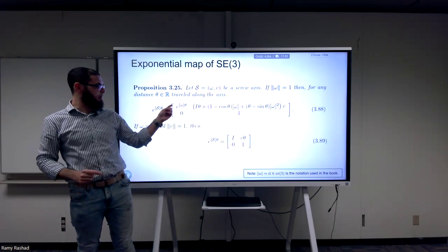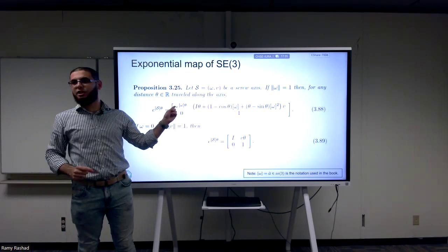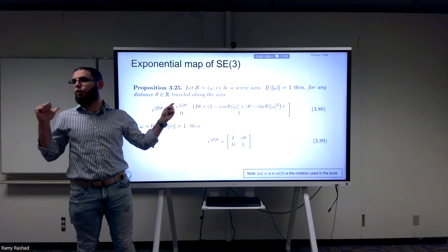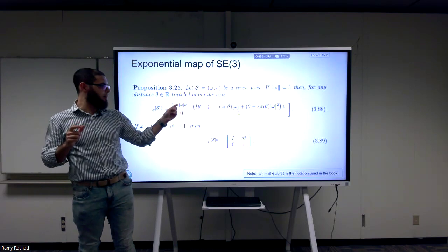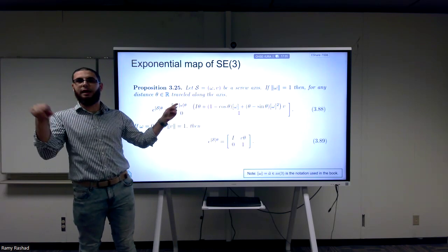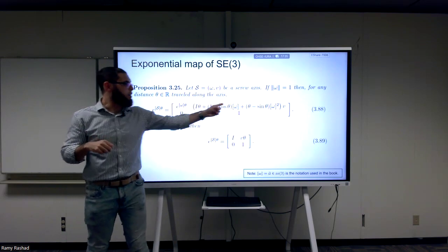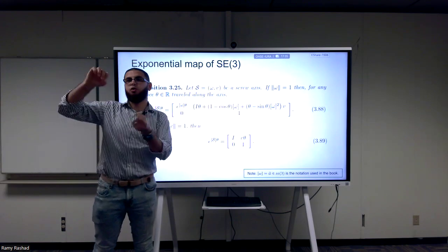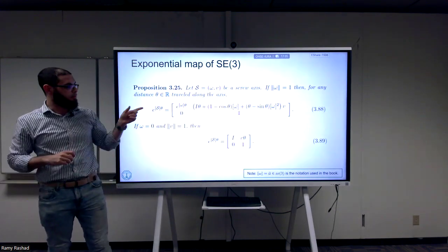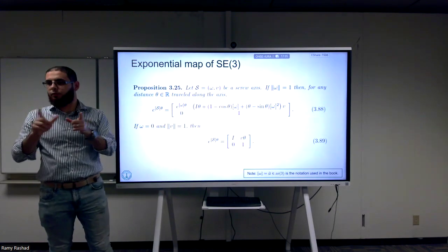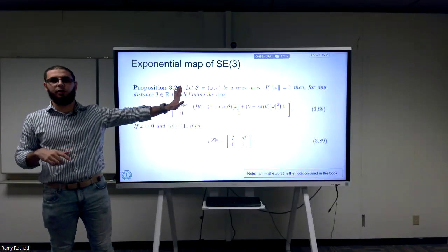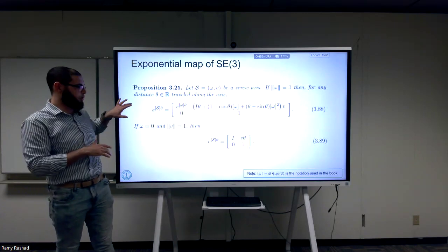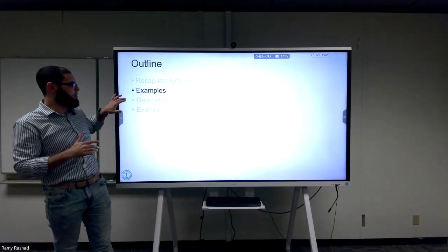This expression is the same. So we have here a rotation matrix. How do we calculate this part? By the Rodriguez formula, because the Rodriguez formula would take an angular velocity, and you can calculate with it a rotation matrix, while this term in the end will just give us some 3 numbers that would correspond to some translation of the 2 frames, of the 2 bodies, with respect to each other. This is something you can just plug in the computer and it will do it for you. This is inshallah what you're going to be doing in the assignment.